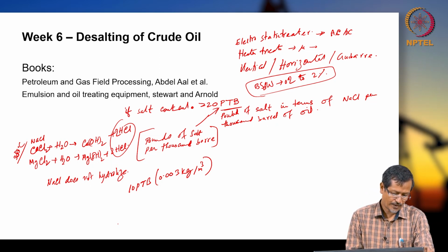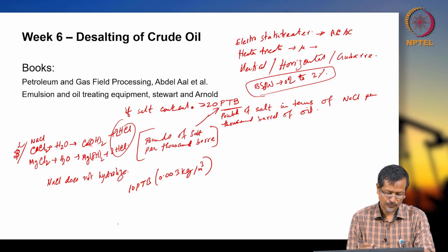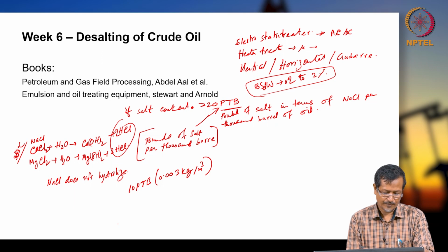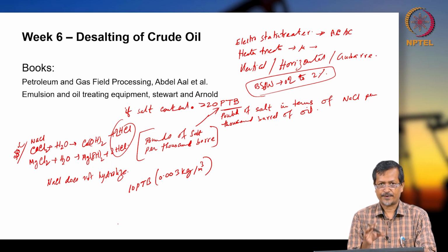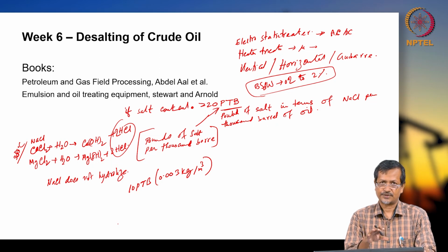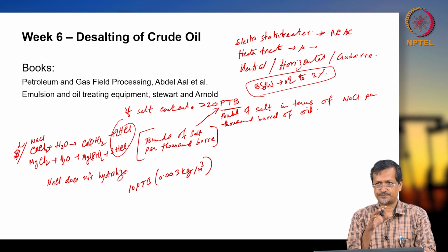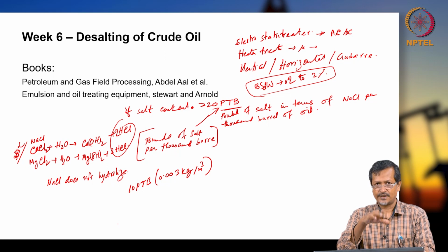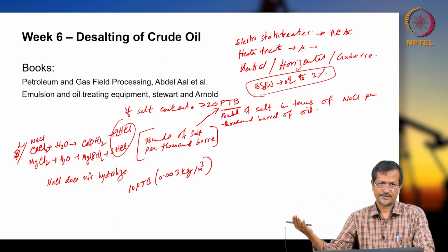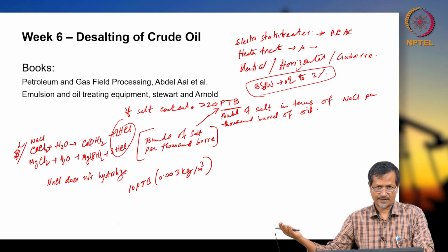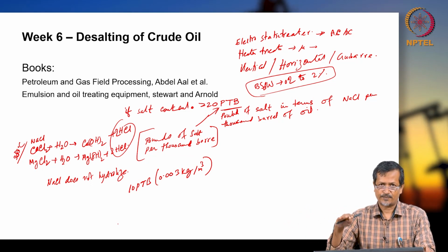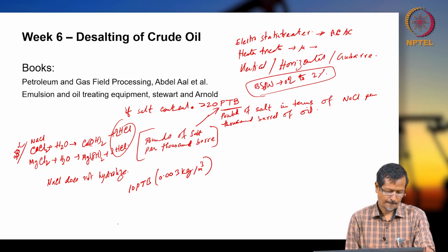Because very little water is required, the crude oil is pumped through the desalter at pressure above its bubble point pressure. Okay. So, above bubble point pressure you are pumping fresh water and crude oil. So, pressure you are increasing a little bit, then this fresh water and crude oil, both will get mixed somewhere. That mixed fluid again you are giving to some electrostatic treater and other treating mechanism, and you are separating the remaining salt, and you are reducing salt PTB to 10 or lower.